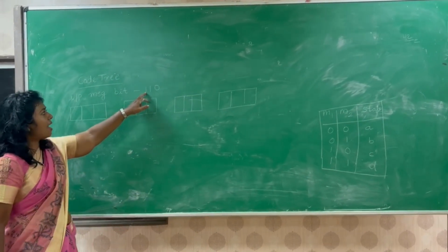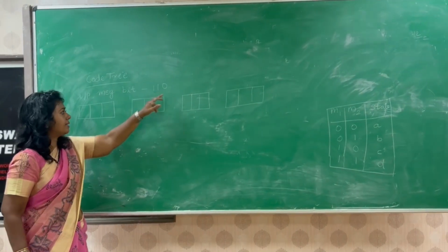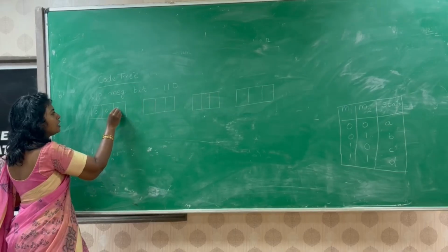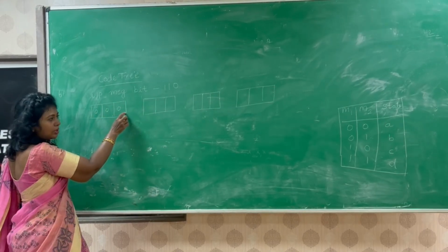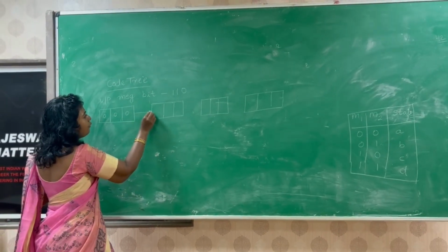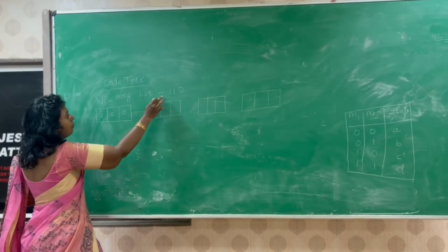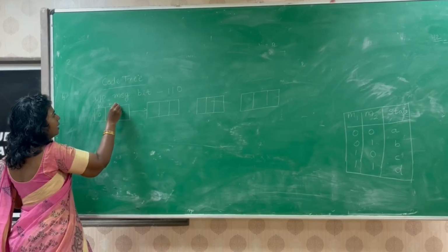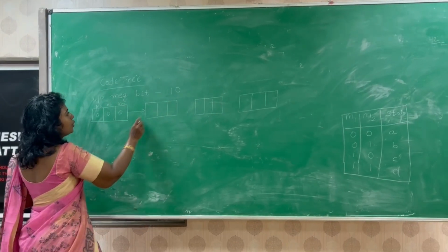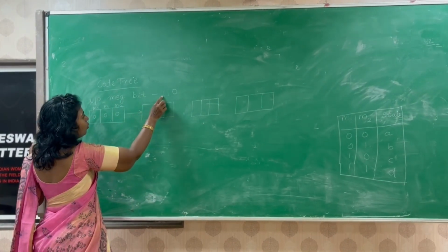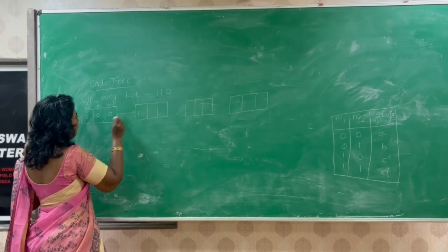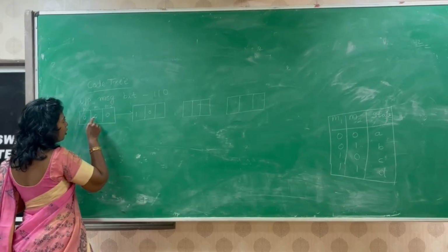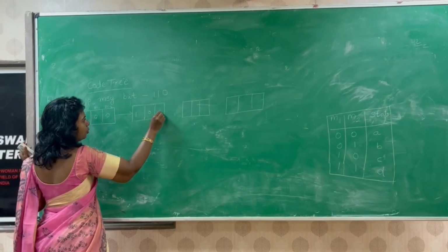So we have the input bits 1, 1, 0. During the initial stage, all shift register contents are 0, 0, 0. During the first pulse, bit 1 enters M0. The content of M0 goes to M1, and the content of M1 register goes to M2.